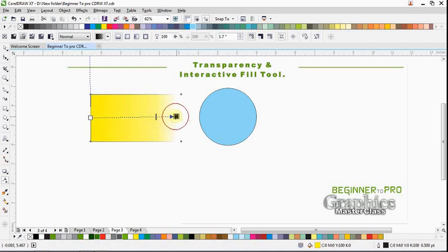You can also shift this place to make it half transparent or any amount you want. You can also determine the percentage of transparency of that particular side. From here you can say 50% transparent. Okay, now it's 50% transparent. You can say 90% transparent. It's now 90% transparent. So you can also toggle with this one too. Let's try it out and see how it works. So you see the whole body of it is becoming transparent. So that is how you can play with it.